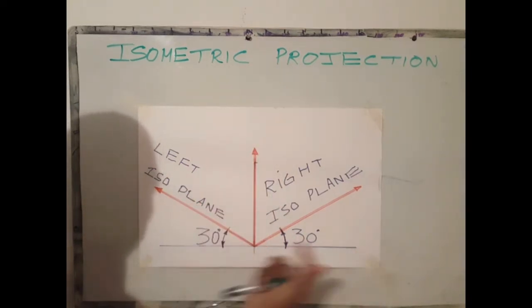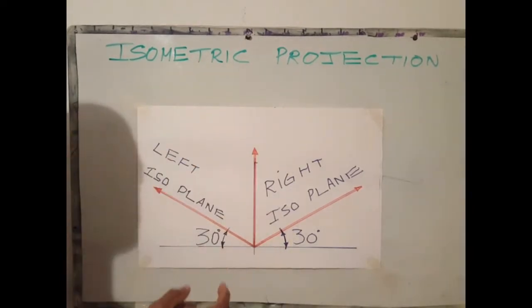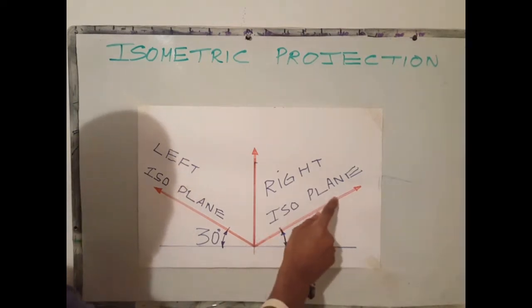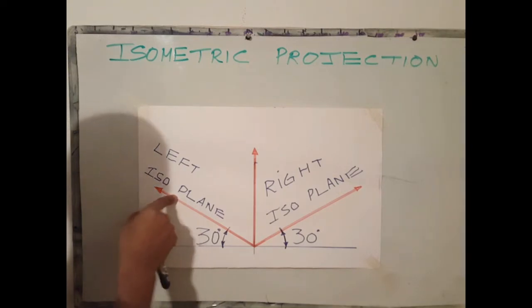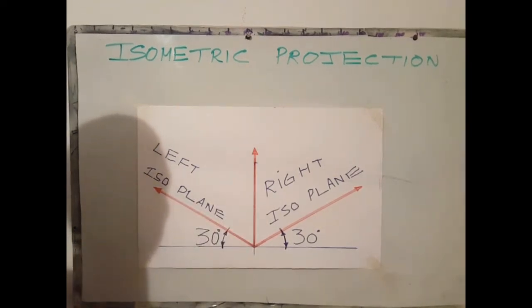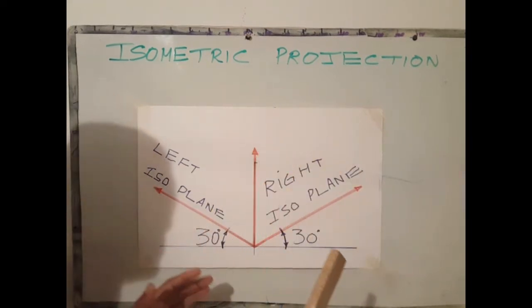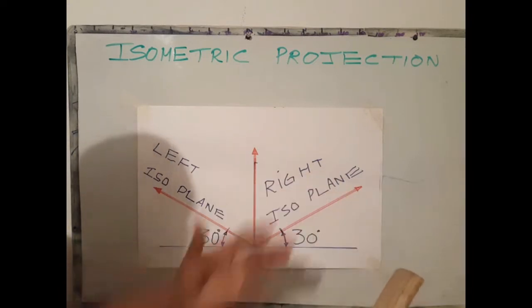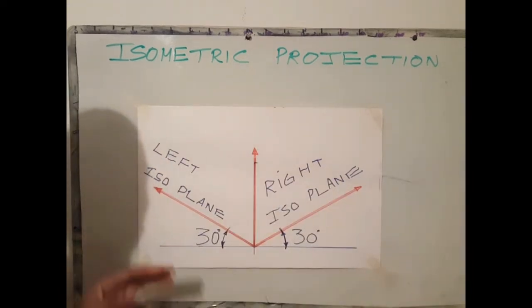That would have been the second step, once you have established your datum line. Next step would be to mark off your length on the right plane, length on the left plane, and your total height. It's always good to mark off your total length, width, and height before we start cutting out any section. It makes drawing very simple.